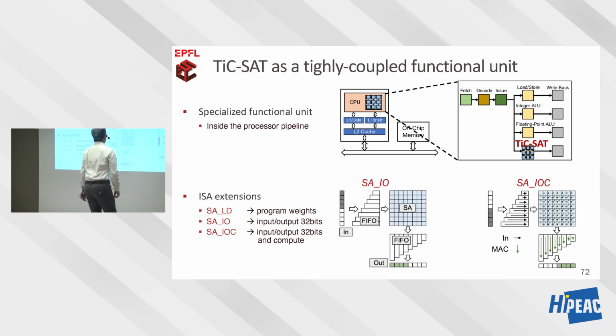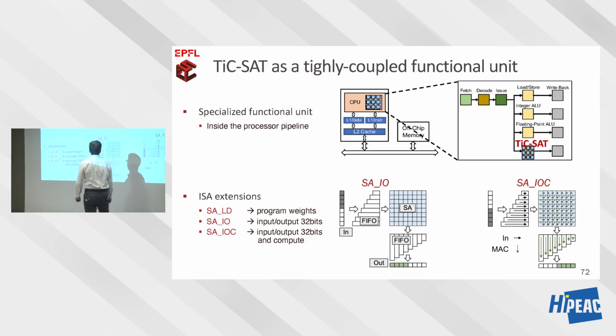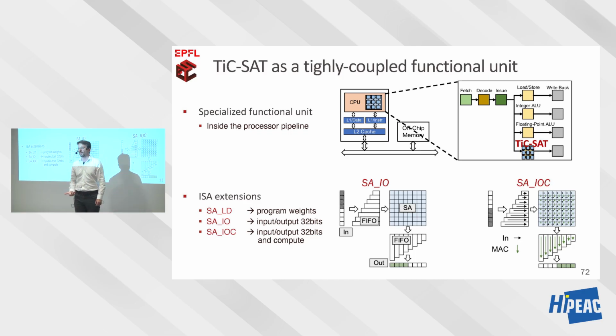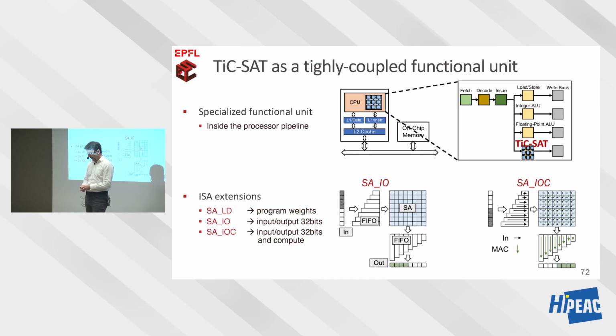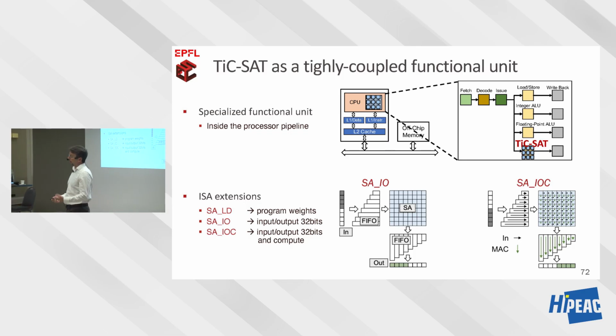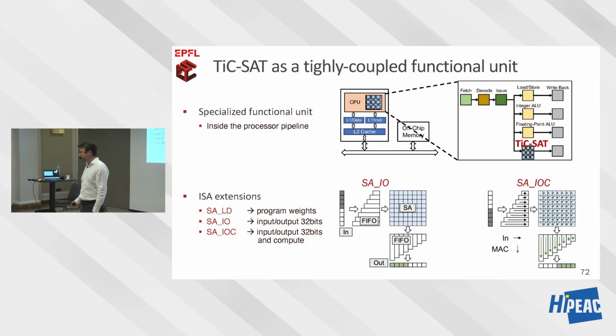The other question you may have is, so at the very beginning, what do I read out? Because all these FIFOs, the registers, etc., imply a delay. The answer is we don't read out anything. We can just discard the values which we read out, and at the very end, whatever input we put into the systolic array is basically meaningless. We can just pad the input and output, but we will see that this is not that bad, both from a runtime and an energy perspective.